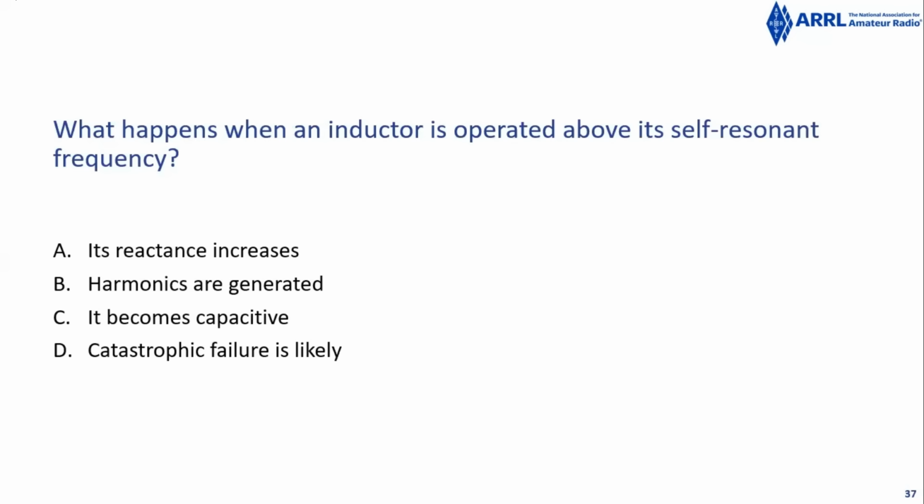What happens when an inductor is operated above its self-resonant frequency? It becomes capacitive. Remember, an inductor above its self-resonant frequency becomes capacitive, and a capacitor becomes inductive above its self-resonant frequency.